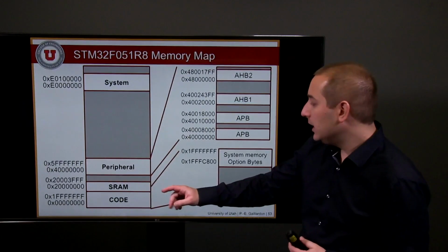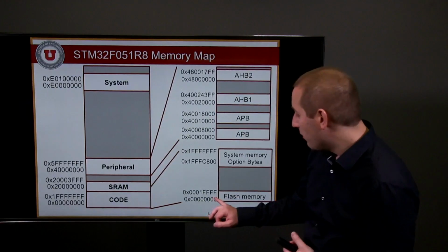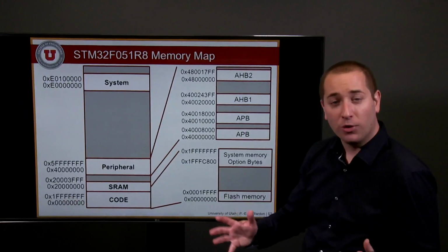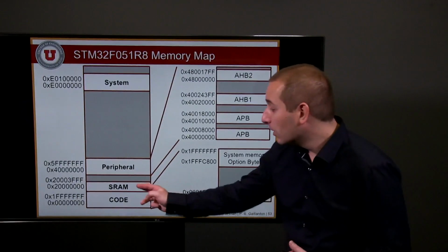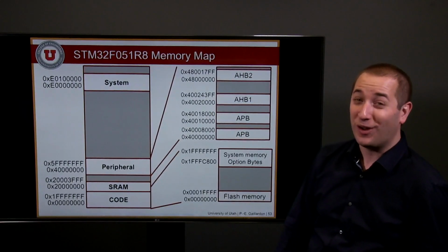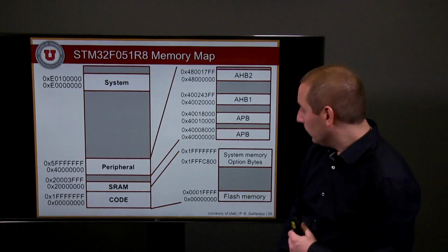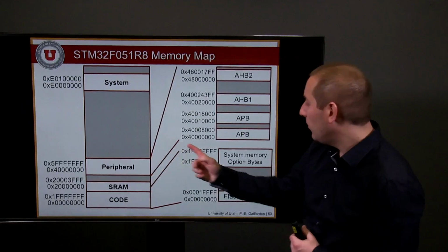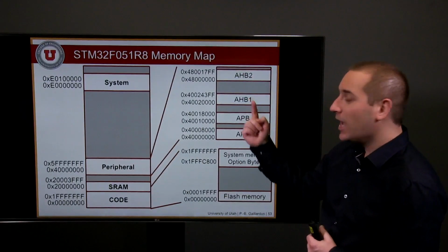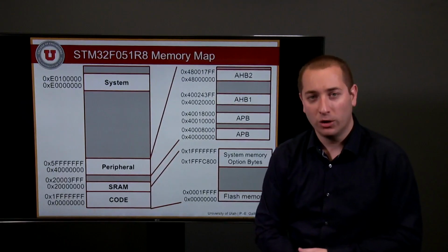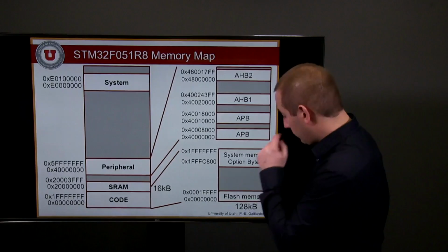This is directly followed by your SRAM, and as you can see, we have a very limited amount of space because we're limited to only a couple of kilobytes of every single memory system, definitely not 0.5 gigabytes. The same goes for your peripherals, where the peripheral address space is divided into several regions for the APB and AHB buses. We're going to talk a little bit more about that right now.